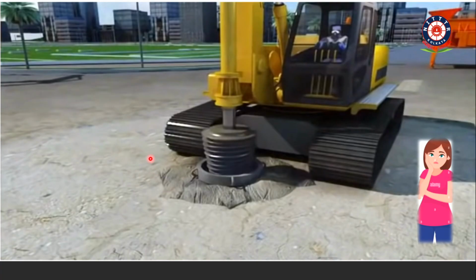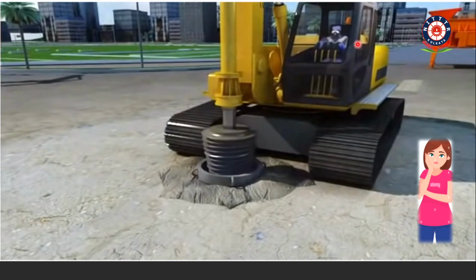Then your bore hole is started. You can see drilling progress is going on to the required depth. Because this is a rotary method, you will be measuring whether the bore hole is going to collapse, you can clearly monitor everything, and you can also get the water table. This method we are using in the metro foundation.